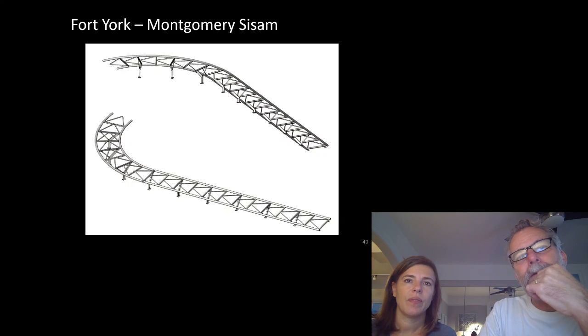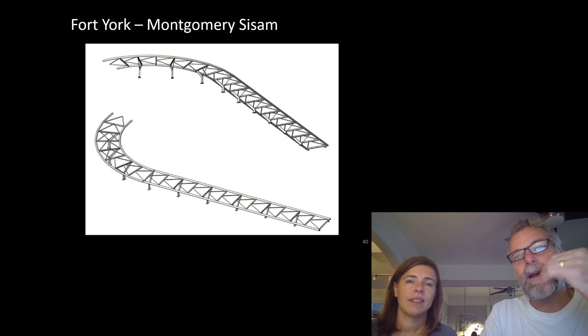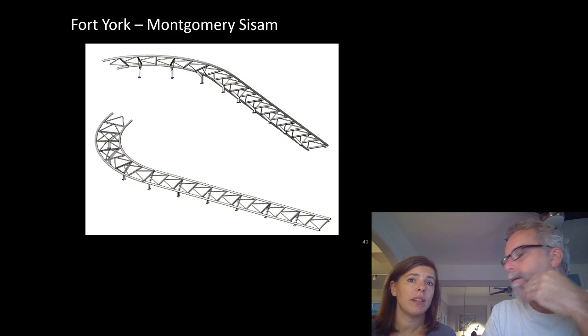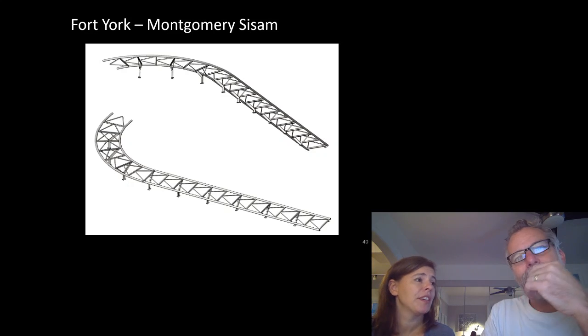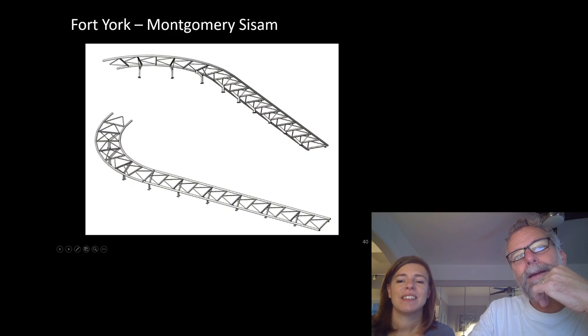And these were the abutment wraps. This we've included for fun, in a way. For one, to show you the kind of infrastructure that has to be built to accommodate the abutments. They're also each little mini pedestrian bridges. They really are, and so we detailed them in the same way. It's the same two tubular sections with the K bracing for the web.